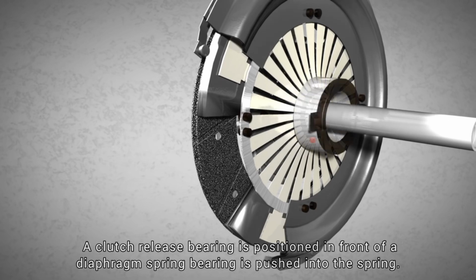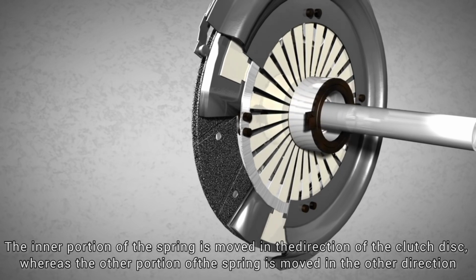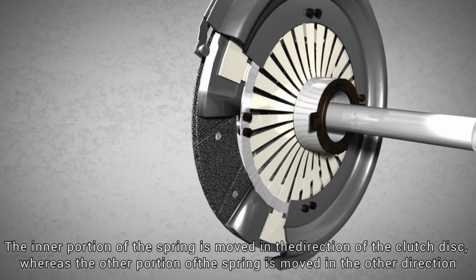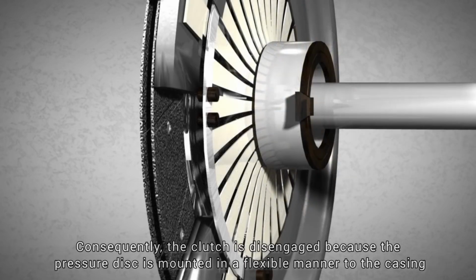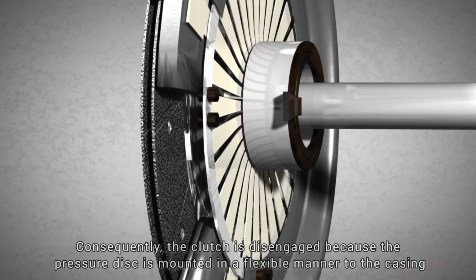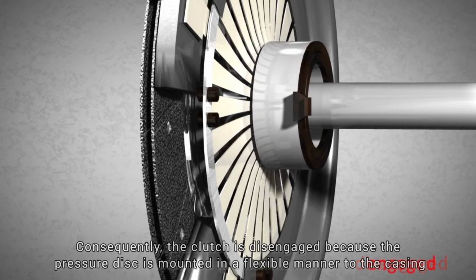A clutch release bearing is positioned in front of a diaphragm spring. The bearing is pushed into the spring. The inner portion of the spring is moved in the direction of the clutch disc, whereas the other portion of the spring is moved in the other direction. Consequently, the clutch is disengaged because the pressure disc is mounted in a flexible manner to the casing.